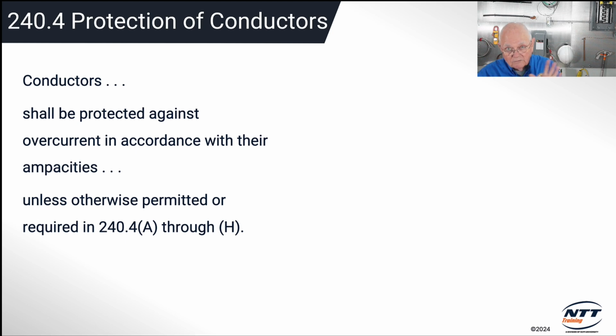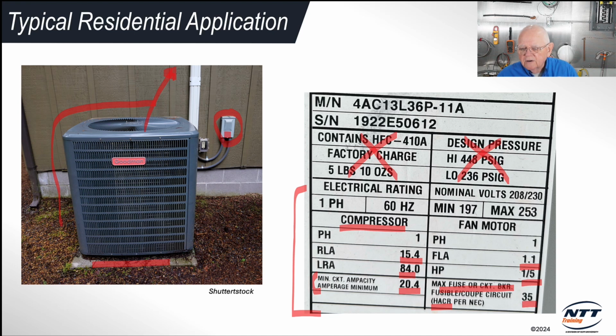So in this case, we said what was our LRA on this motor? We said it was 15.4 amps. So maybe at 15.5, 16, 16.5, whatever it is it's set for, some percentage over that 15.4 that the manufacturer has decided, that overload device after a certain period of time will open up and de-energize my motor for me.